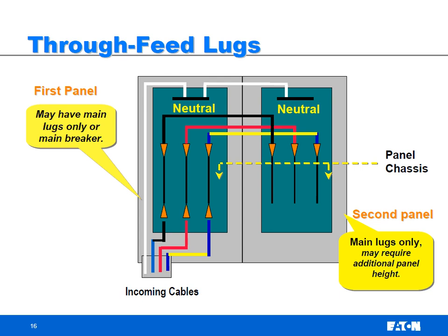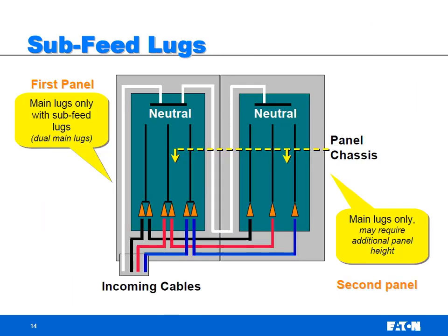The other one, can you flip the back? Where would the breaker be in now? On the top? Here you can't put a breaker, because this is going to take two cables. So if you got a 100 amp breaker and a 100 amp cable, you go upstream to the main switchboard, and that would have to be your disconnect. That's one of the reasons probably why this is not that common.